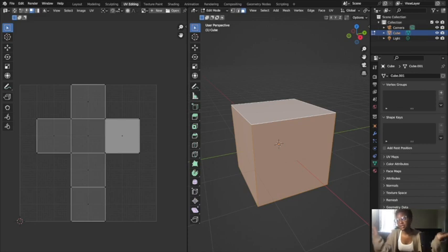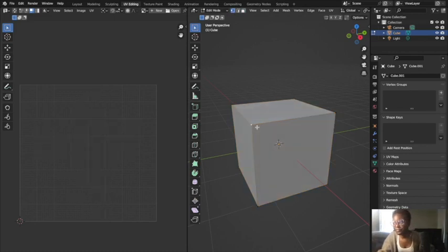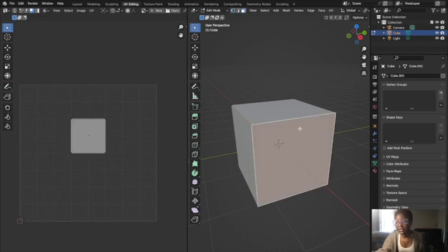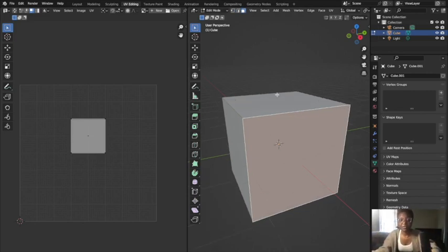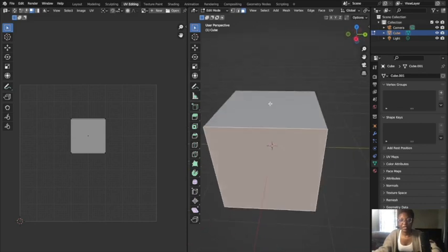And this again shows you the area of the UV editor. We're in edit mode right now, so you can select a vertice, face or edge, but basically the workflow is there's many approaches to doing this. So you can mark seams on the mesh to create a separation, because right now the mesh is together, right?